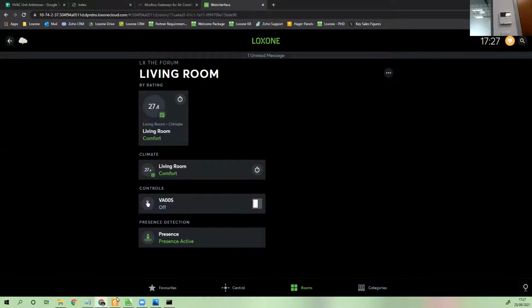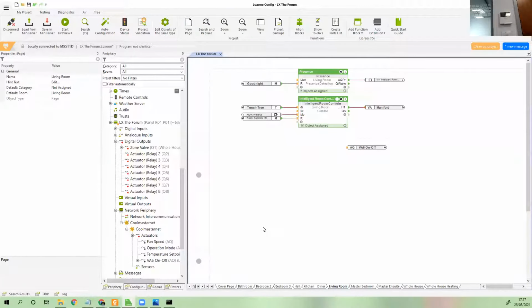And then the final bit, which you might need to set, we don't on our particular aircon system, is the louver position. The reason we don't need to set a louver position is because we have ceiling mounted vents that have no louvers. On a domestic AC unit, you might have those louvers that move up and down and you need to set a louver position. I normally just have it constantly pointed up. That's my personal preference. So I just put a constant onto it.